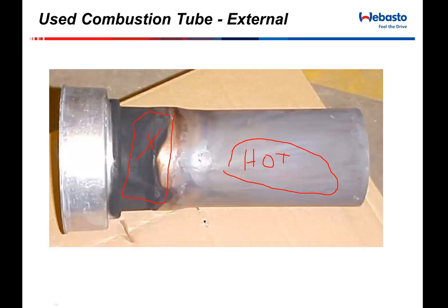If you're seeing carbon building on the back end of this thing, one of two things is happening. Either I have a nozzle in there which isn't atomizing properly, so I'm not getting a good spray pattern through the middle of it, or I have a voltage problem where that fan motor isn't pushing that airflow fast enough or hard enough through it, and it's allowing that flame to more or less back up.